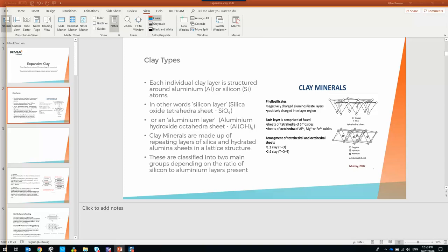And also with the plumbing, they came out of the building on the right, then they wanted to shortcut and go underneath it again. And again, that's just asking for trouble. You've got a service trench heading towards your building and under it. Bearing in mind this is a raft slab. So we told them to go around, and we also tell them to put clay bridges across the bedding layers where those magenta sections are.